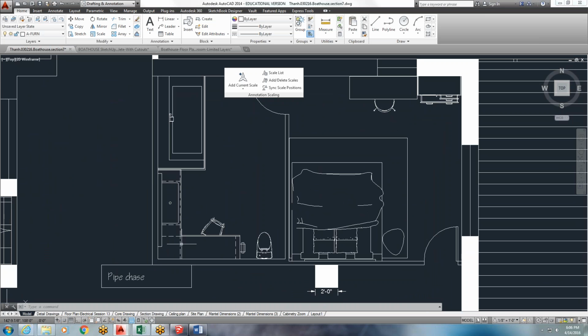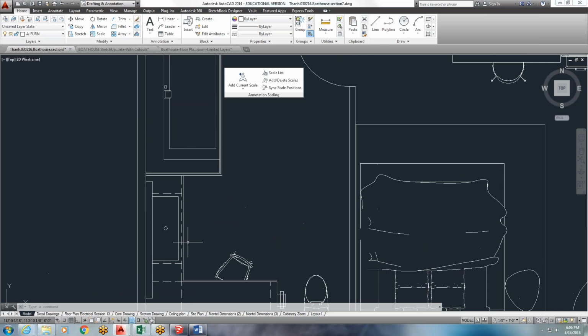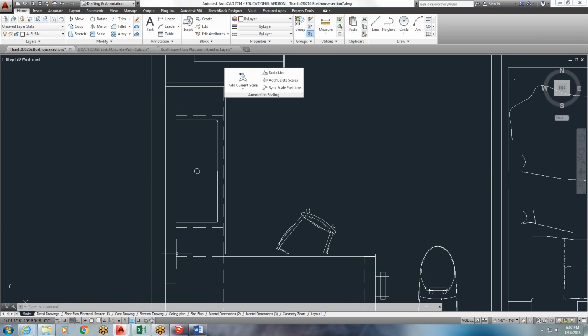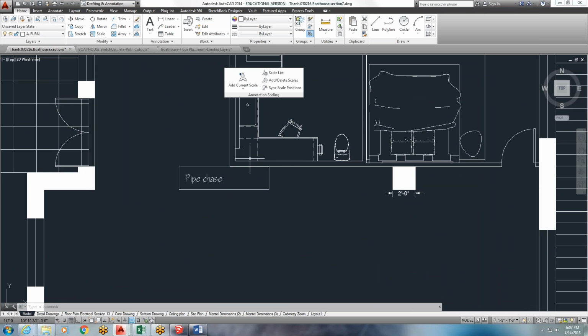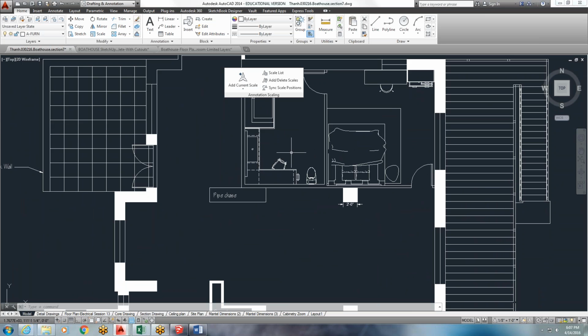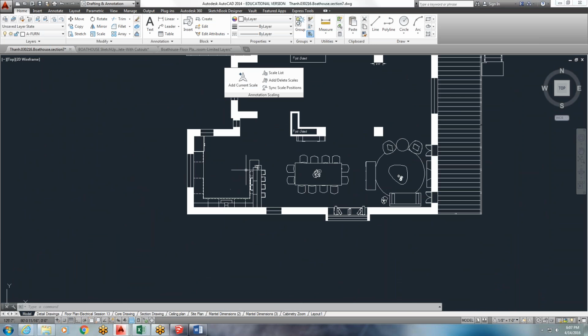But if you are going to draw your own bathroom, you need to make sure that your cabinets are the proper depth and that you're showing a cabinet with a countertop line. More important than even the depth is that you're showing me the dashed lines for what's going on underneath. If you have drawers, and we might get into labeling next week, but for now I'm more concerned about the placement of the furniture items. So I want to make sure you have those things if you've planned to do your own kitchen and bath. But otherwise, you can copy mine and save yourself some time.